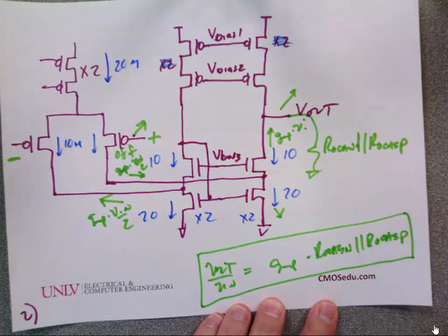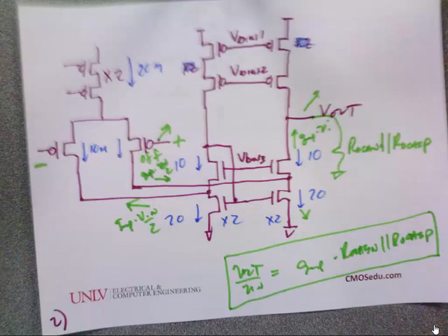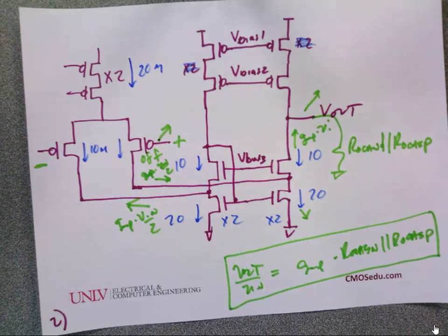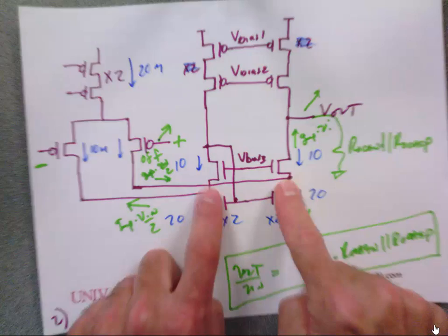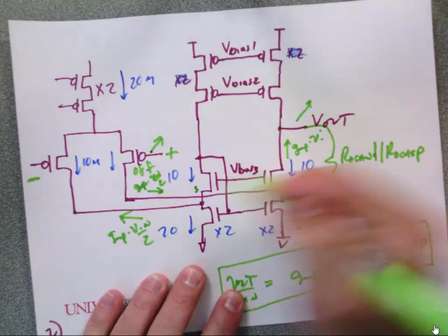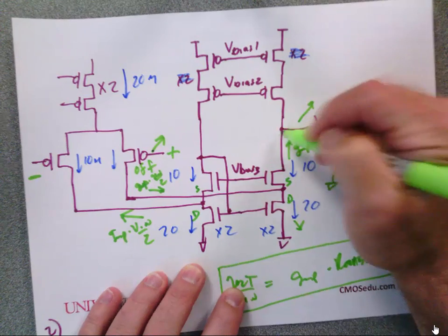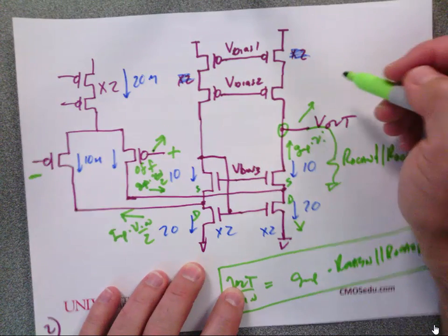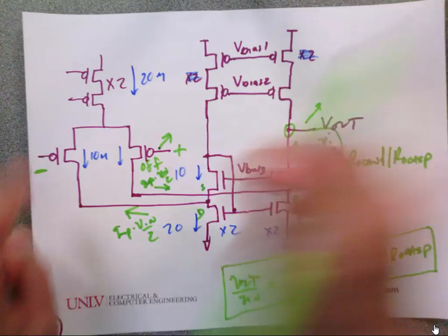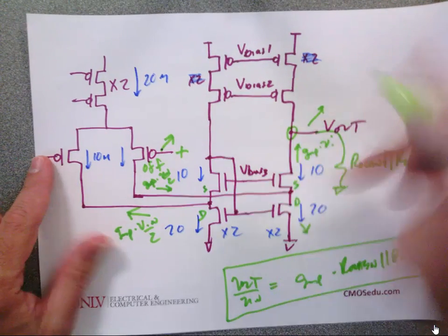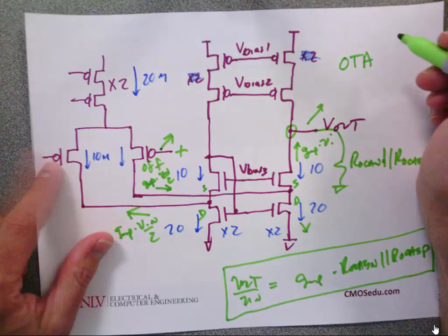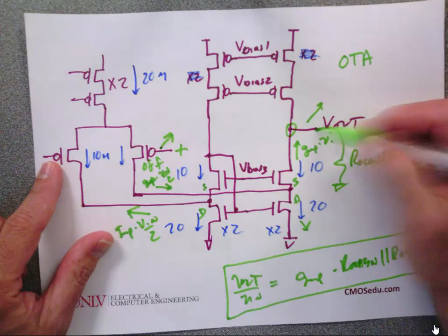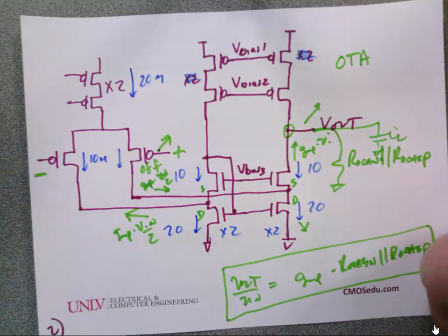And I want to drive that yet again. I mean, you just had a quiz on diff amp operation, right? Okay, so let's go look at it. So how many stages is this? It's one stage because these are low impedance nodes because of the sources here, the drains. And so there's one high impedance node, which is this one. And so a circuit with only 2 high impedance nodes, the inputs and the output, is called an operational transconductance amplifier. And the reason we like those is because they're easy to compensate with a load capacitor. And I'm going to show you that right now.